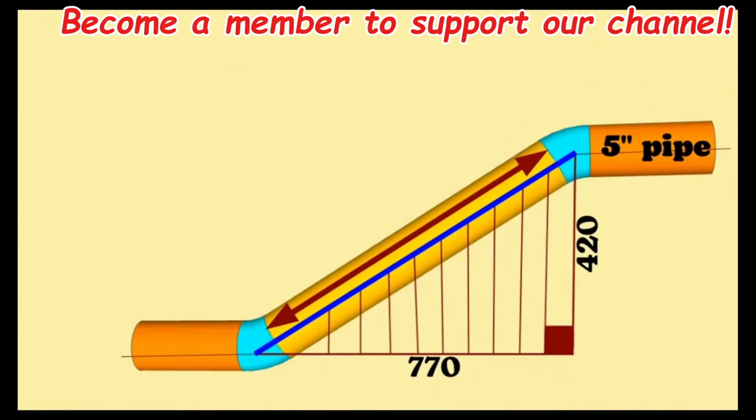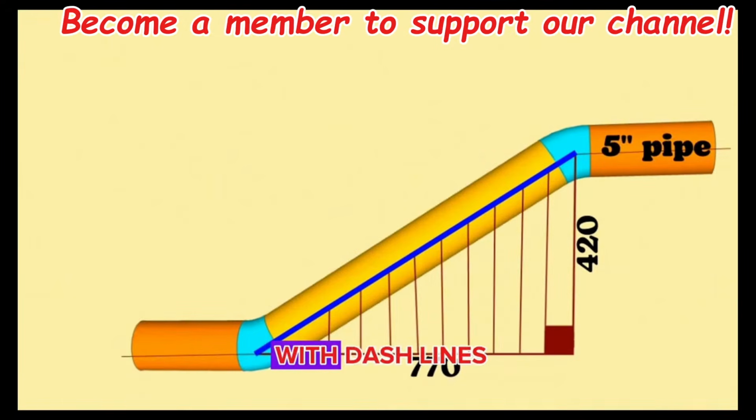As you can see, the 5-inch pipeline comes first horizontal, then vertical up with 420 mm, and then continues horizontally again. A right triangle is formed with dashed lines after the pipeline rises vertically 420 mm. The hypotenuse of this right angle triangle is the distance between the elbows in the pipeline.